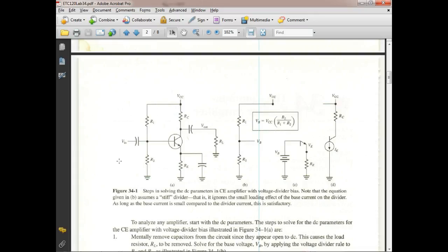You understand? If you put the black lead on the cathode and the red lead on the anode, then it's going to measure, for a silicon, about 7/10. For germanium, it's going to measure about 3/10, right? If you put it backwards, it's going to measure an overload. So you just can't put the meter on there both ways to check a diode. You got to do what?